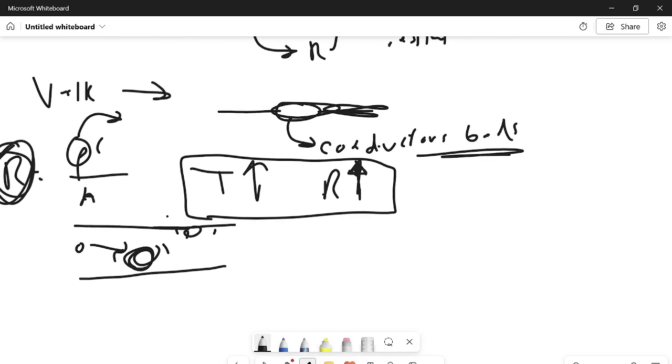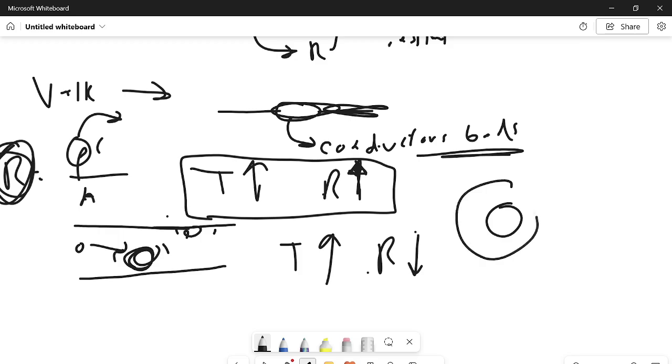The interesting thing is, well, we already talked about it, but for semiconductors, as temperature increases, their resistance will decrease. I already spoke about why: at high temperatures some of the electrons are freed, and so the current will increase because there's more charge carriers in the circuit, allowing there to be a higher current.